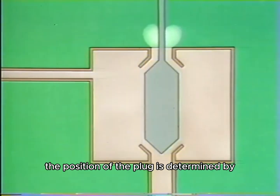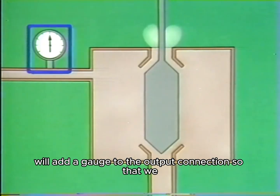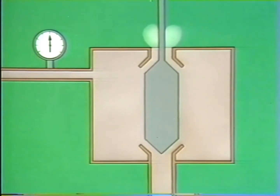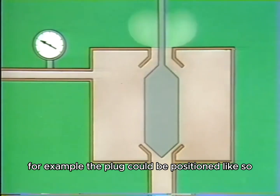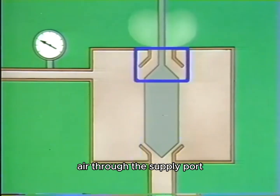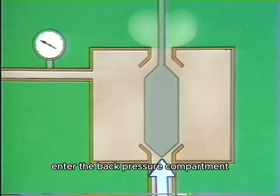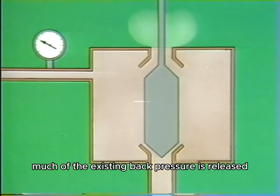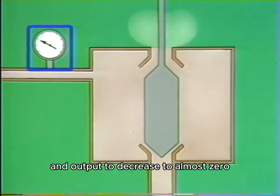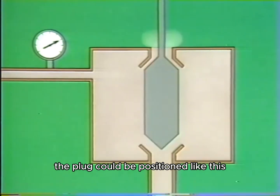The position of the plug is determined by the movement of the input mechanism. We'll add a gauge to the output connection so that we can see how back pressure changes in relation to the operation of the pilot valve. For example, the plug could be positioned like so. In this position, the plug reduces the flow of air through the supply port and opens the exhaust port. As a result, less supply air is allowed to enter the back pressure compartment. Much of the existing back pressure is released through the exhaust port, causing the back pressure and output to decrease to almost zero. On the other hand, the plug could be positioned like this.